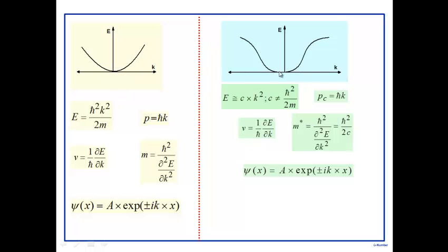What one is saying is one will approximate this by a parabola here. Now, of course, note that as you apply a force, K increases here. It may happen that as you apply a force, K may go over here. And then, of course, what it means is your effective mass approximation is breaking down. All right. But we'll do some simple calculations and show you that under typical cases, K will lie very close to the bottom. Okay, we'll show you that. So the takeaway from here is the electron can be considered as free, but with an effective mass m star here. Okay.